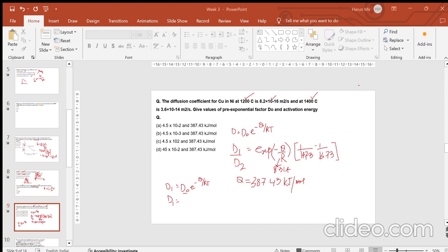Okay, so we have a general formula for a non-steady state equation like this, where A is actually your concentration at the surface, and we can do the A and B part later. For this equation, we have to use it at a certain position x, so we can find x. This is our aim: to find at what position we will have the concentration as 0.4. We also have A and B values because they are related to your gradient, but this D is something we do not know. We only know D naught, so first we should find D.